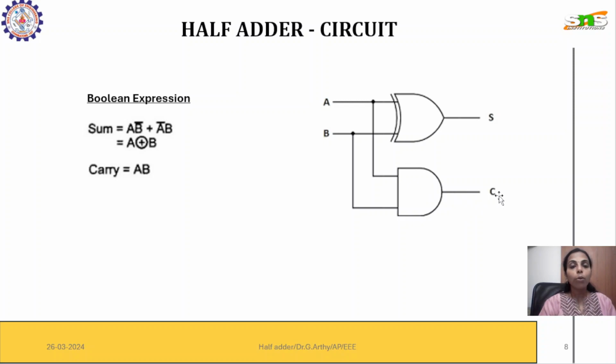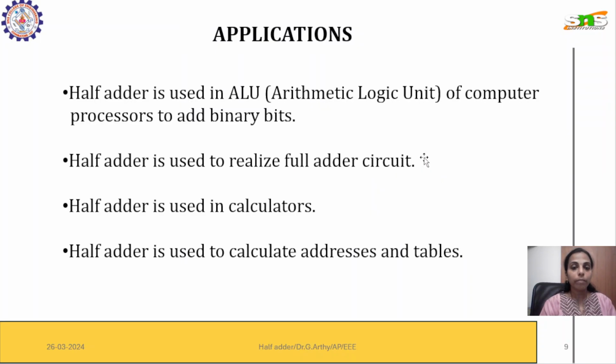So this is how a system has to be designed in digital electronics. Any kind of system could be designed using the same procedure. First, the conditions have to be written as a truth table. From the truth table, we have to draw the K-map. From the K-map, the Boolean expression has to be derived, and for the Boolean expression, we'll be drawing the circuit which could be realized.